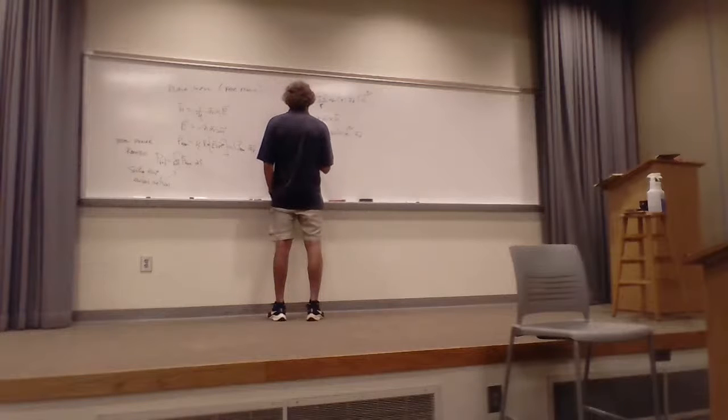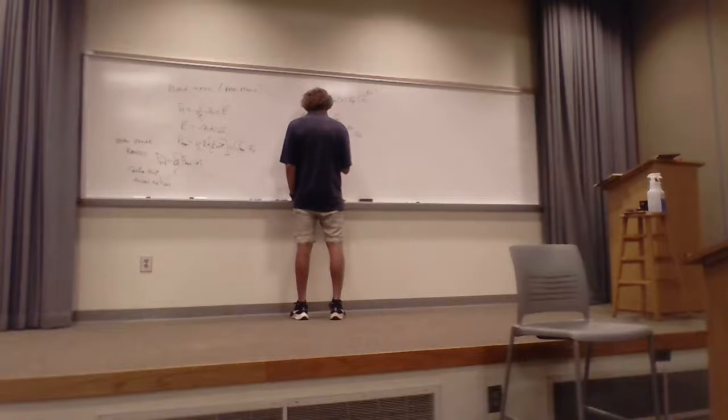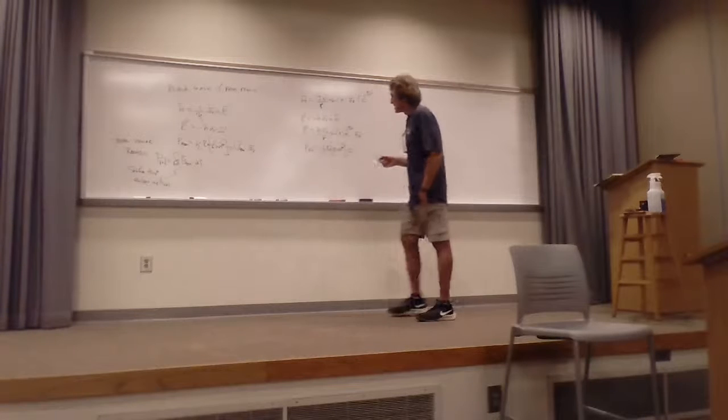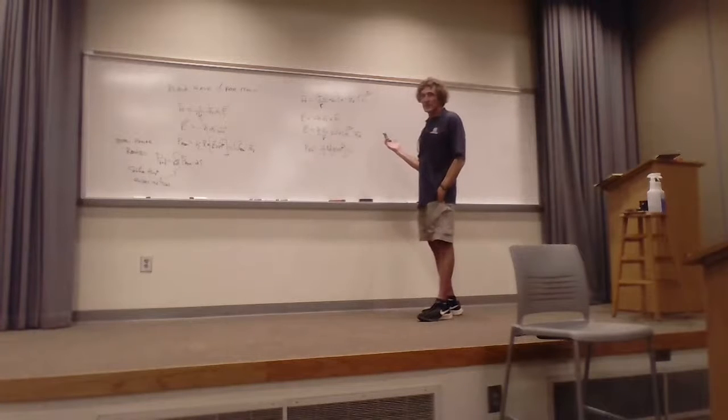So then when I get the propagating electric field, or the power density, P-av, that's going to be 1/2 the real part of E cross H conjugated. And when you do this, I'm just going to tell you how I do this. I know there's 2 ways to get the amount. This is a lossless system.